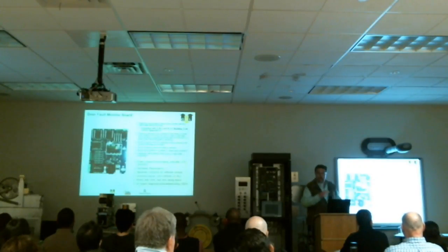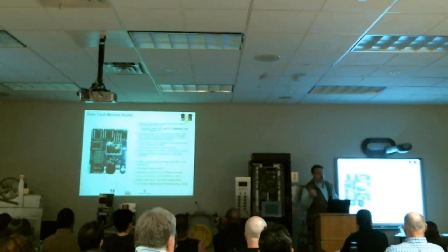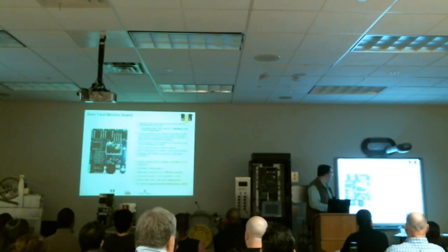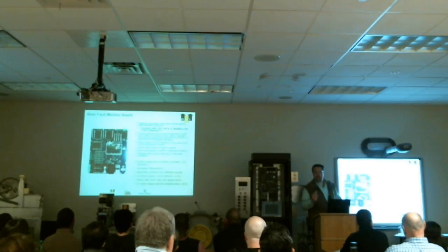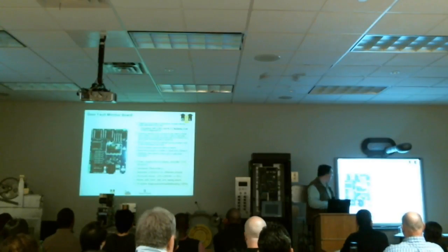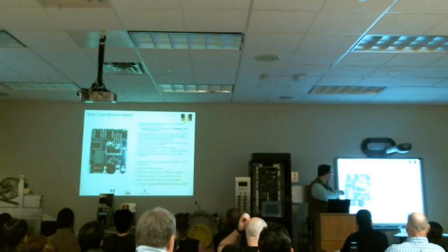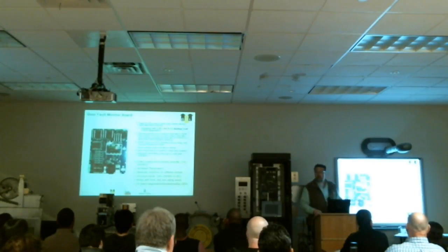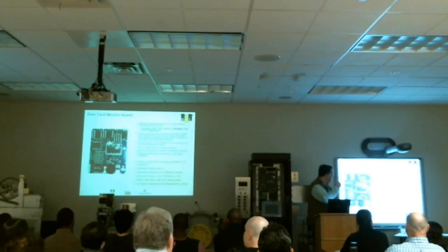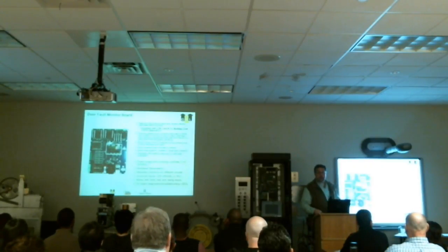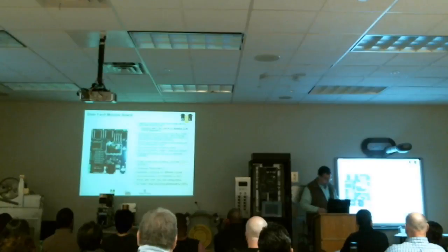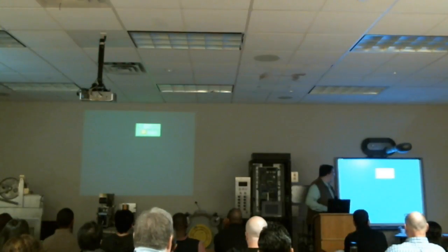We have separate commons for our circuits, because you will have separate commons depending on the circuit that we're going to be working on there. It's designed for front swing doors and also for front and rear. And we have an onboard diagnostics LED, LCD indicator, as well as an onboard buzzer to indicate when there is a fault. It says, hey, I got a problem over here. Come and take a look, see what's going on. Okay? So we have our own door fault monitoring board that we can adapt onto foreign equipment to meet the requirement.